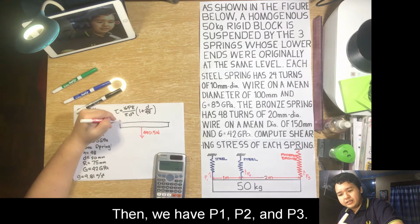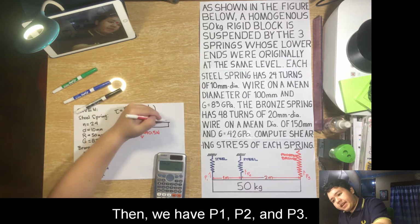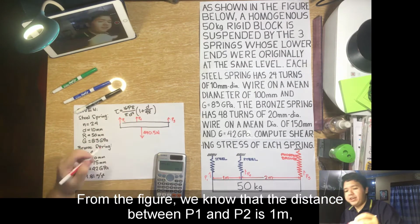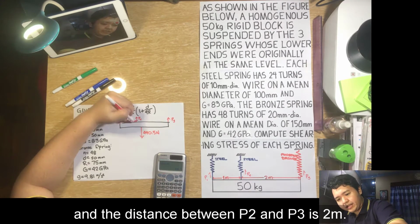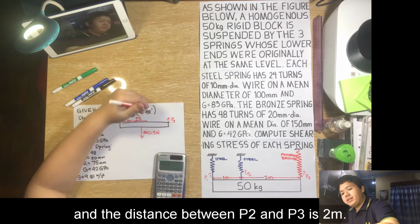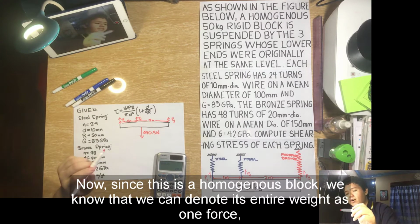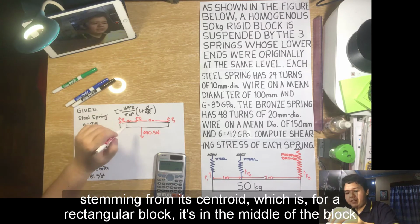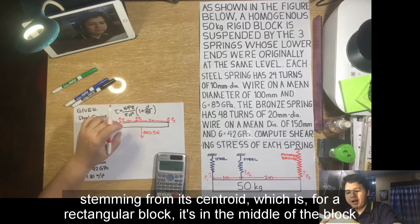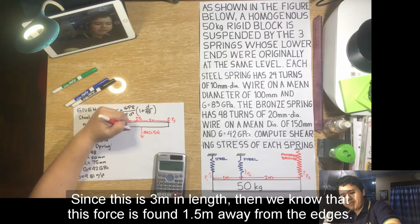Then we have P1, P2, and P3. From the figure, we know that the distance between P1 and P2 is 1 meter. And the distance between P2 and P3 is 2 meters. Now, since this is a homogeneous block, we know that we can denote its entire weight as one force stemming from its centroid, which for a rectangular block is in the middle of the block. Since this is 3 meters in length, then we know that this force is found 1.5 meters away from the edges.